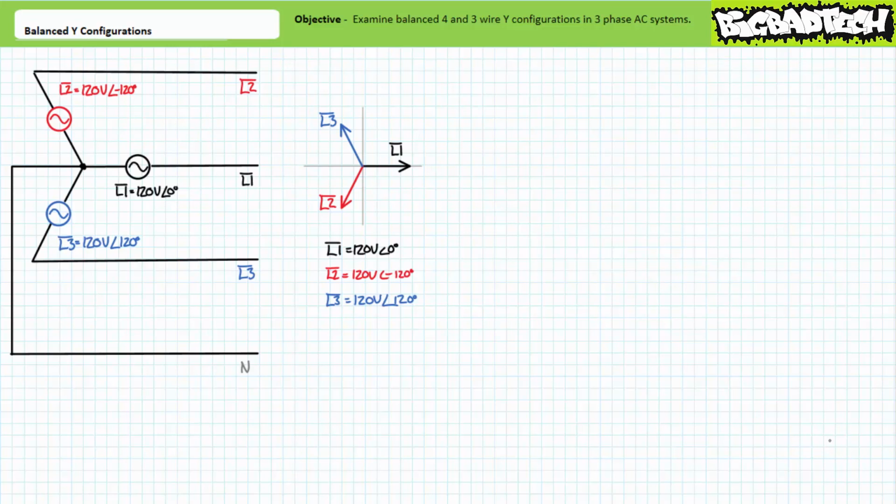After satisfying this first question, I then ask myself the simple follow-up. What current does a load in this particular system experience? Does a load directly experience full line current, or does it experience only a portion of line current? The answers to these two simple questions are of tremendous benefit to any three-phase AC circuit analysis scenario. Once these initial questions are answered, the active analysis is merely application of single-phase AC circuit analysis principles, like Ohm's law and the power equations, techniques you've had ample exposure with by now.